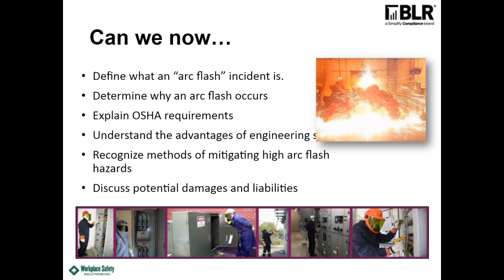And then what causes it? We went through a whole bunch of different scenarios of what can cause an arc flash event, and it's really what we do with the equipment, or if equipment fails and it goes to ground. It usually starts off with a phase to ground fault, and then it travels to phase. Usually that's how it starts.